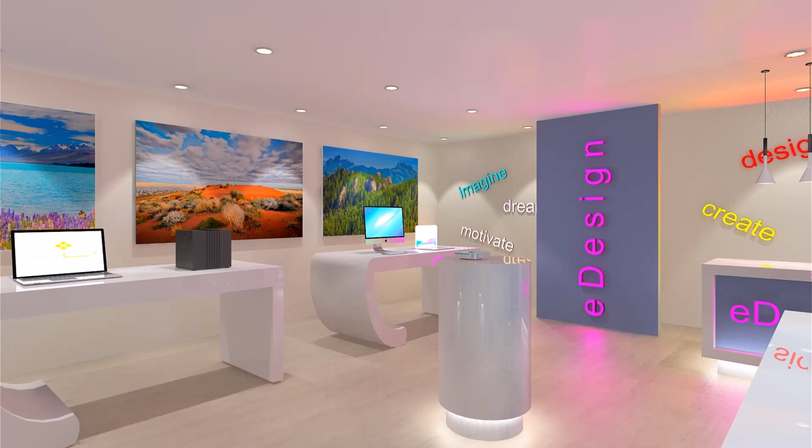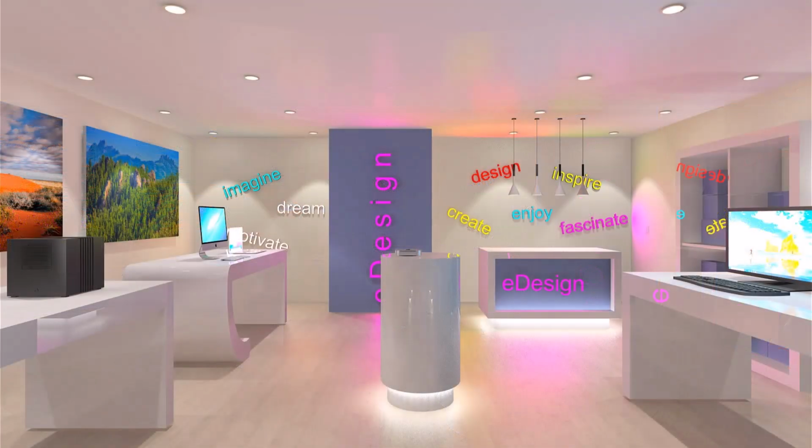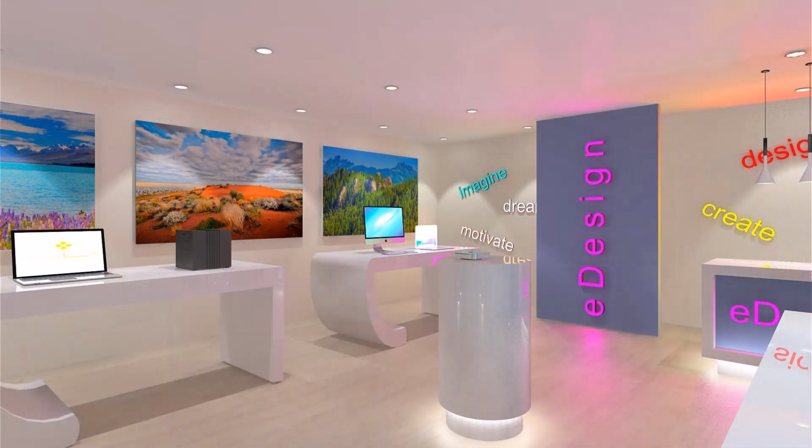Let's summarize what we learned during the workshop. As we have seen, creating a good photorealistic image requires several steps. Let's sum them up. First, let's use at least 3 layer groups per room. Set up at least 2 or 3 perspectives that effectively showcase the scene. When setting up the perspective, the object and camera values should be between 1.1 and 1.4 meters, and the camera angle should be between 60 and 75 degrees. Adjust the position of the sun so that it's not too contrasted and doesn't dominate the entire scene.